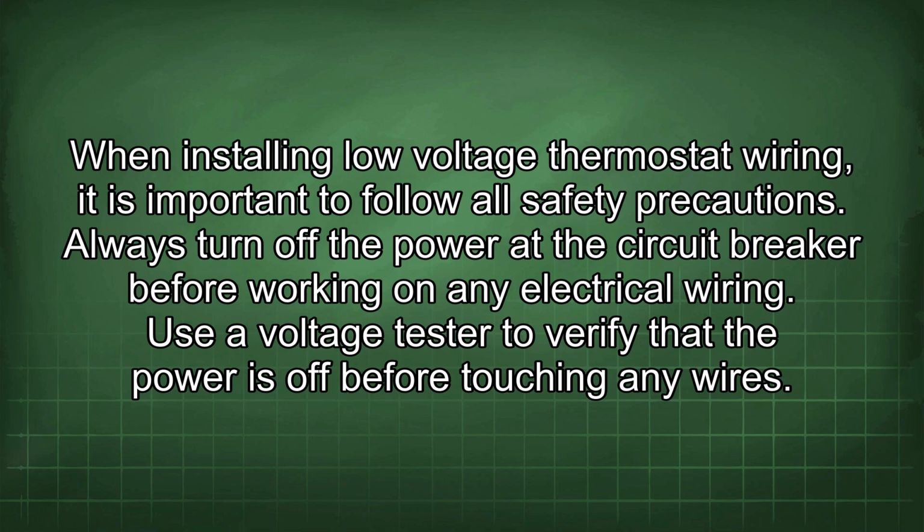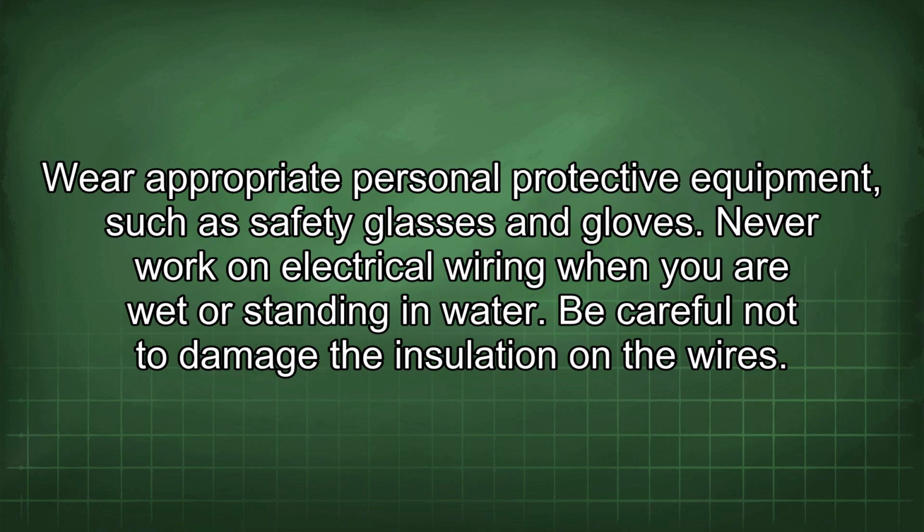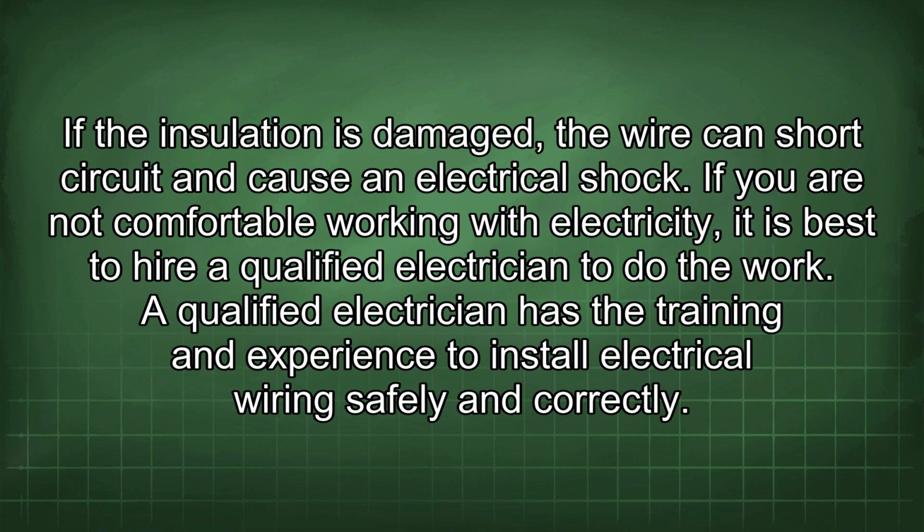Always turn off the power at the circuit breaker before working on any electrical wiring. Use a voltage tester to verify that the power is off before touching any wires. Wear appropriate personal protective equipment, such as safety glasses and gloves. Never work on electrical wiring when you are wet or standing in water. Be careful not to damage the insulation on the wires. If the insulation is damaged, the wire can short circuit and cause an electrical shock.